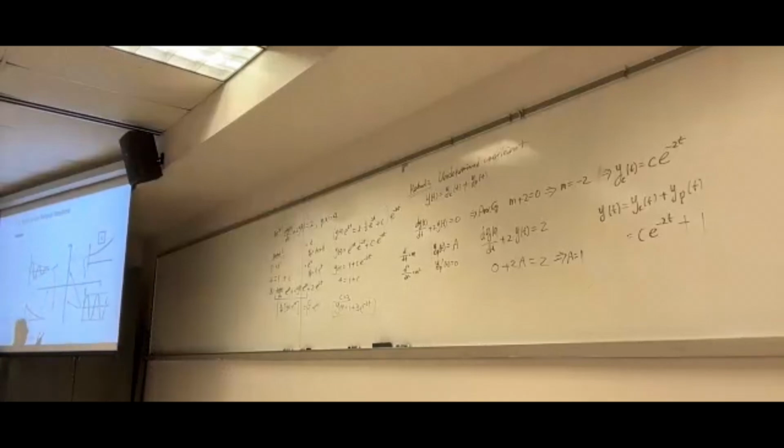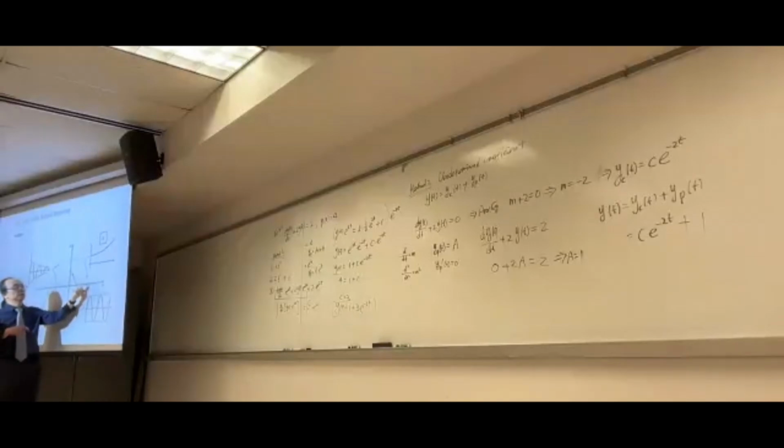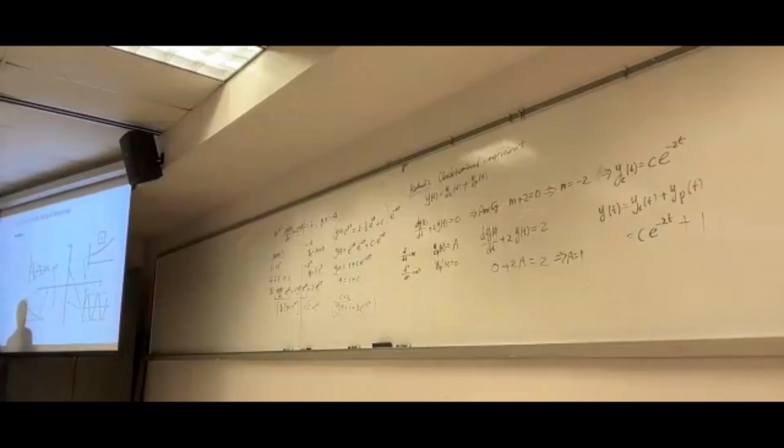However, if the real part is on the positive side, then it's going to go up, and it's unstable. If the roots are purely imaginary, plus or minus j5 on the j omega axis, then we call it marginally stable. We're not going to really talk about that in this class. You will see this again in control.